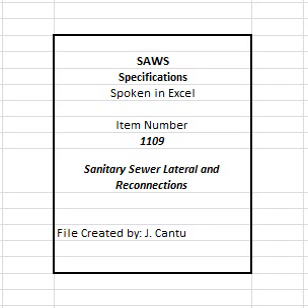F. One or more lateral connections discharging into a common point are considered one service connection. G. The contractor shall not add lateral reconnections without approval of the inspector. H. The inspector may require laterals to be relocated to avoid having more than 2 lateral connections per reconnection. I. Protruding lateral connections, which must be removed to allow liner insertion, are paid as a lateral reconnection, when connected.